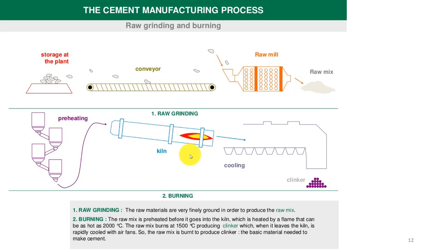After passing the feed material through the rotary kiln, the output product is basically the clinker. The clinker contains the chemical composition in the form of tricalcium silicate, dicalcium silicate, tricalcium aluminate, and tetracalcium aluminoferrate, which I have discussed earlier in the previous lecture. You can go to the previous lecture to revise, in case you don't have knowledge about all these products which are found in the kiln. I will also explain later in these slides how the temperature affects the formation of these chemical constituents.